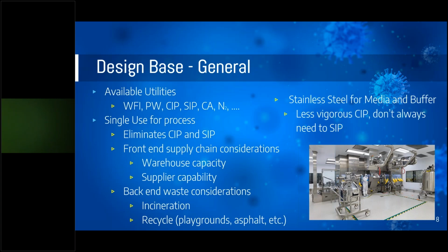The larger you go, it's also more difficult to handle all the different aspects of single use. So that was one consideration. Also, the cleaning involved around media and buffer is often less vigorous, usually just a hot WFI rinse, and you don't need your harsh acid-base cleaning solutions for the media and buffer. So we were able to use the stainless steel equipment while also capitalizing on the benefits of the time saving when it comes to the cleaning. Next slide, please.